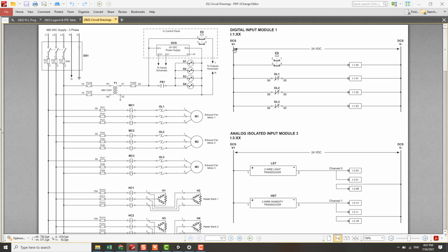Okay, we know that the DC voltage, DC current will source the external input switch or sensor, then it will sink the PLC input load to the ground. Here is not the ground but negative. Negative DC line via the PLC common point.